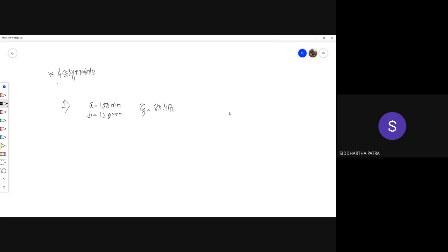So this is basically K. You can immediately calculate the maximum pressure, P double prime, that you can apply, which would be twice tau y ln of B by A. I took B squared by A squared and made it twice ln of B by A.